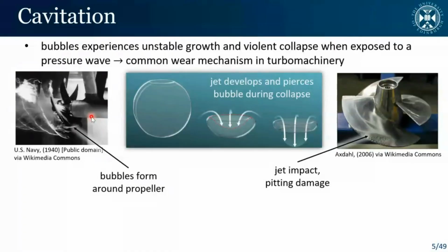During these low pressure phases, bubbles can form, and they expand rapidly. Then as the pressure reaches a maximum again, these bubbles start to collapse. As they do, they don't collapse completely spherically. They have a jet that forms preferentially towards one side, which can impact the opposite bubble surface.